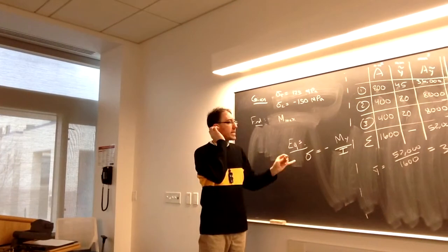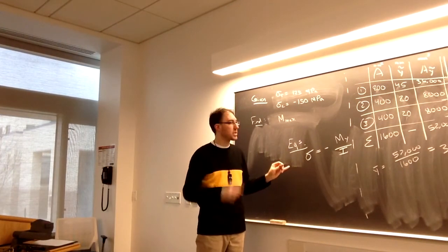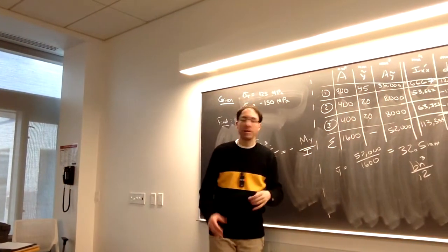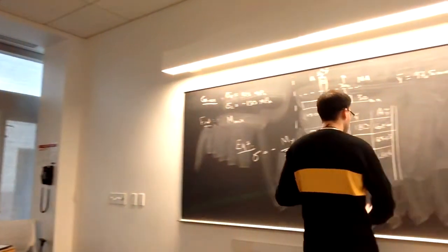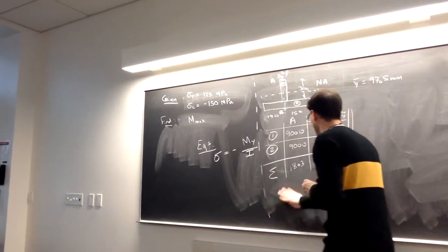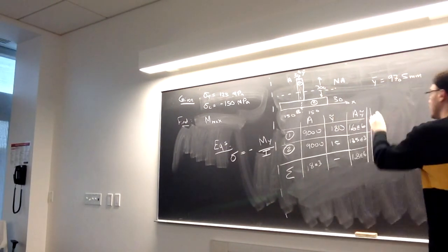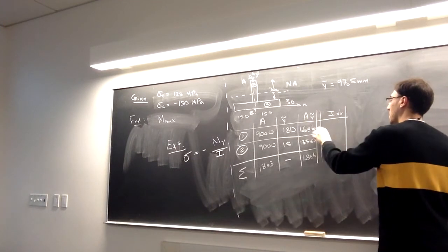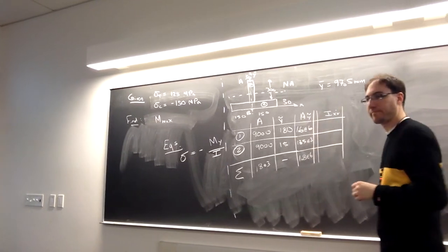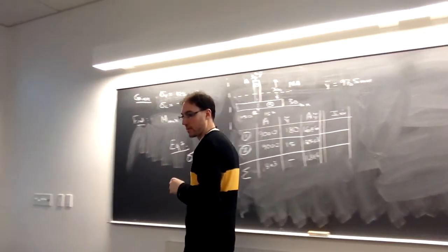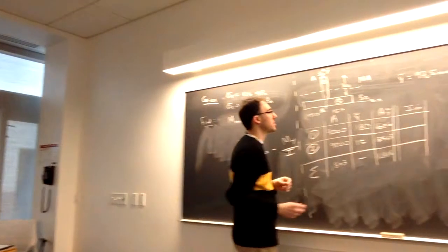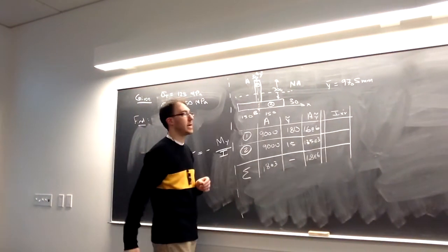The equation we need to use is the same. It's still the bending stress equation. But our calculation for I is going to be different. It'll be a little bit quicker for this one since there's only two pieces. So I decided to break it up with one horizontal slice and one vertical rectangle here.